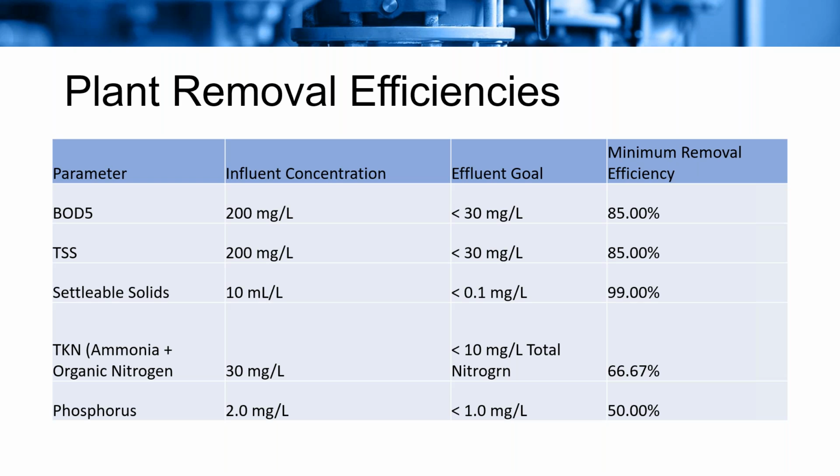Usually go from 200 milligrams of BOD to less than 30, which is part of the 30-45 rule for both BOD and TSS. I'm sorry, I got that backwards. 30 milligrams per liter is your 30-day average, and 45 can be the max for a 7-day average.